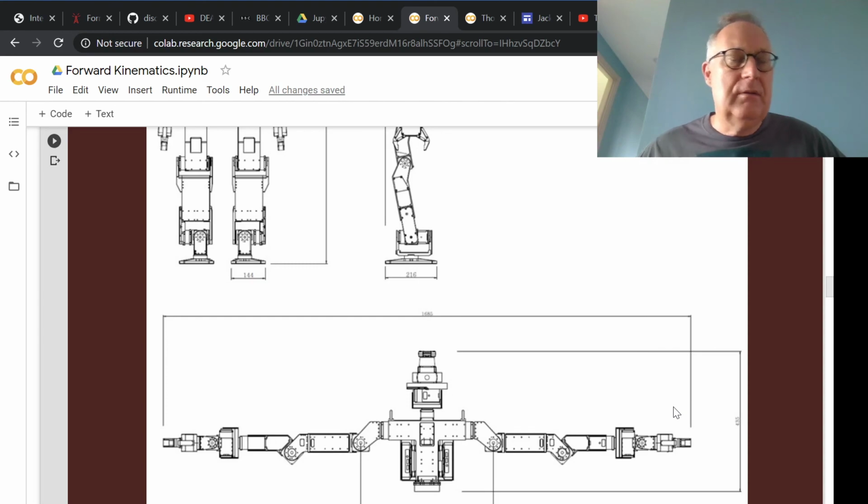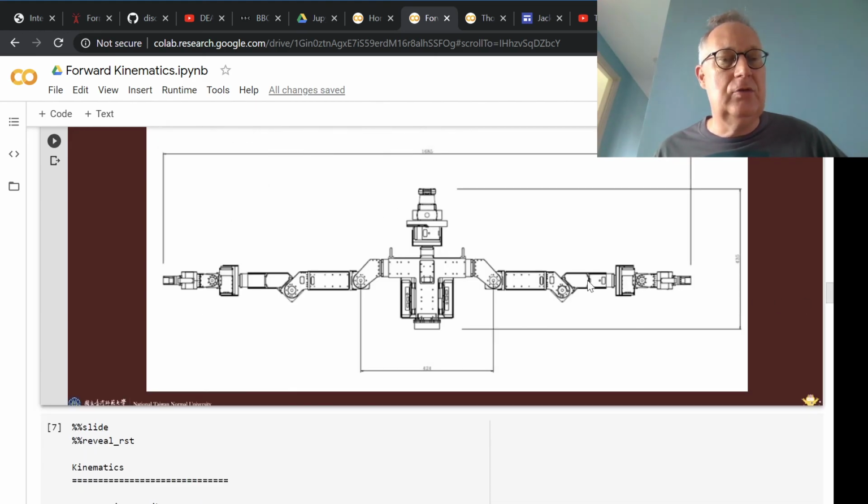So we usually constrain ourselves to the Denavit-Hartenberg convention, which greatly simplifies things and allows us to come up with an alignment of coordinate frames that intuitively makes sense. It's not a burden, it's not an extra constraint, but it actually helps. You would most likely choose these positions for the coordinate frames anyway, even if you were given completely free choice.